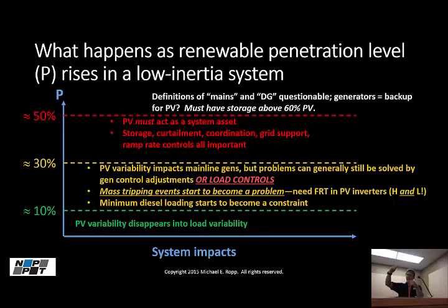You can breach those frequency trip limits, and then you'll lose all your PV, because again, frequency is across the whole system. So you have to adjust your trip thresholds to make sure that the inverters aren't all tripping at 59.3 hertz, for example. Fortunately, with modern inverters, that's pretty easy to do. Just widen the trip set points. One other thing to watch for is minimum loading constraints on your engine gen sets. That can become a serious issue as PV penetration goes up.